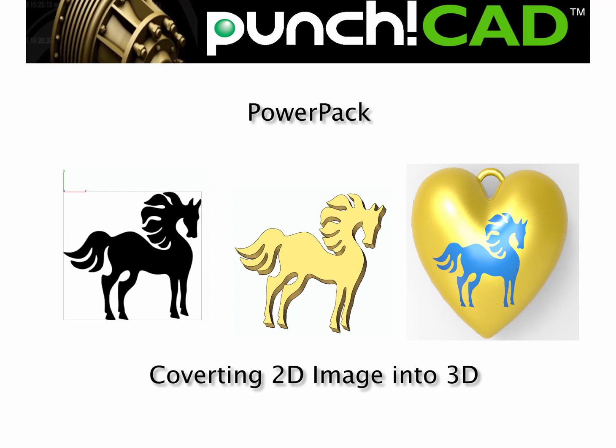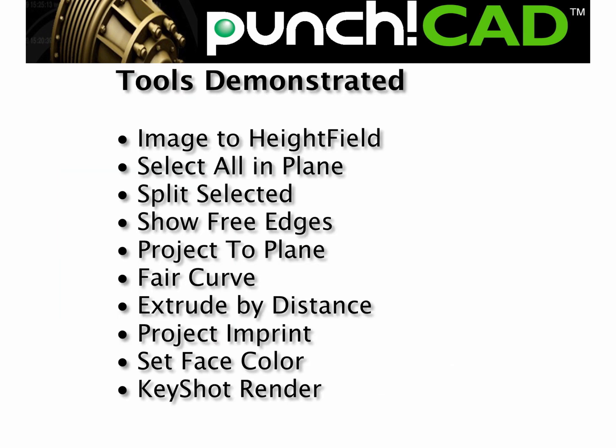In today's video demonstration, we're going to show how you can take a 2D image and convert it into a 3D model suitable for extrusions or projections into 3D parts. Some of the tools that we're going to demonstrate will include taking an image and converting it into a height field, selecting all the facets in the same plane, splitting facets, showing free edges, projecting curves into a plane to